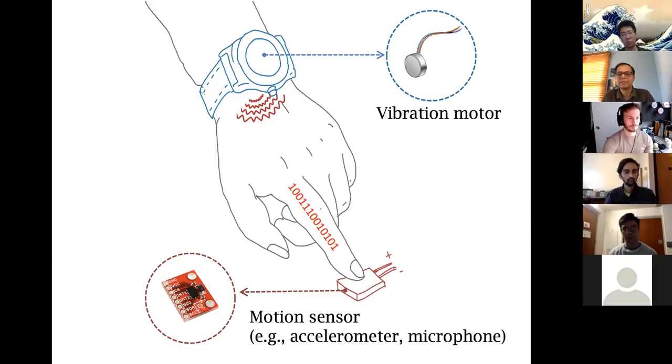Right? So if you have a bit string of 100111, you vibrate for a little bit of time. That'll be your symbol interval or your data bit interval. And then you don't vibrate for 2 time units, 100, and then again you vibrate for 3 time units. That's your Morse code. That'll give you some data, right? And your accelerometer will get some vibration signal, then it will be noise, vibration signal, and you're getting data out of it. Right? But you can do much better.